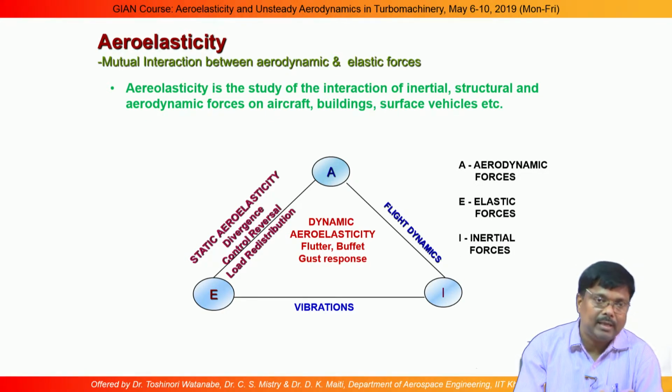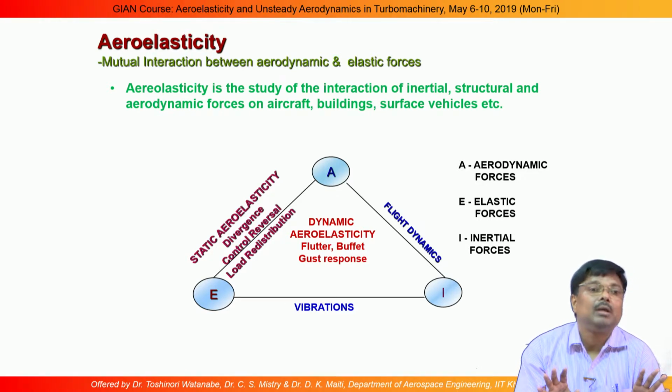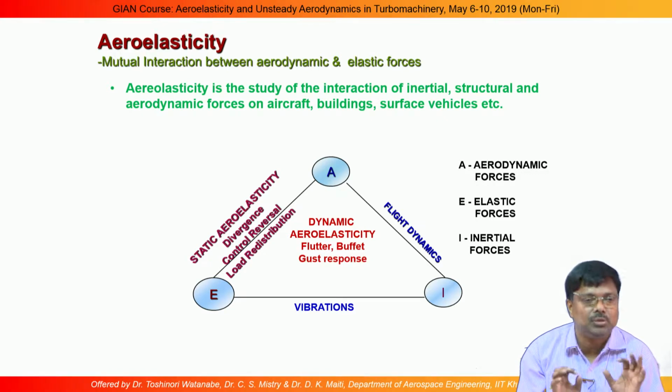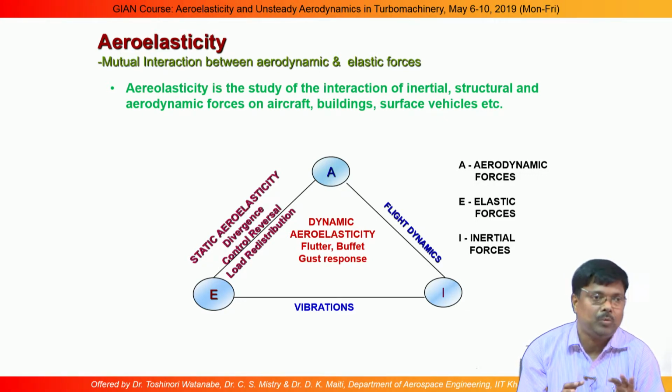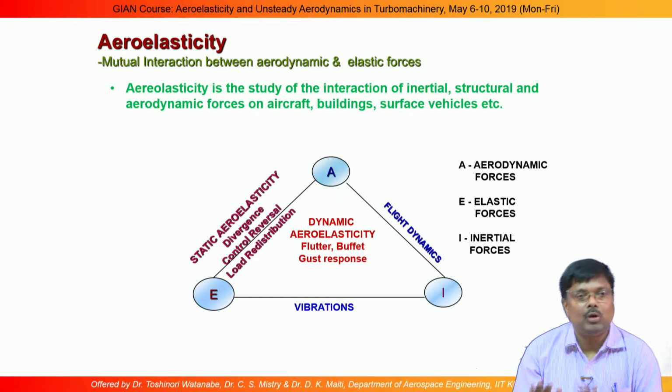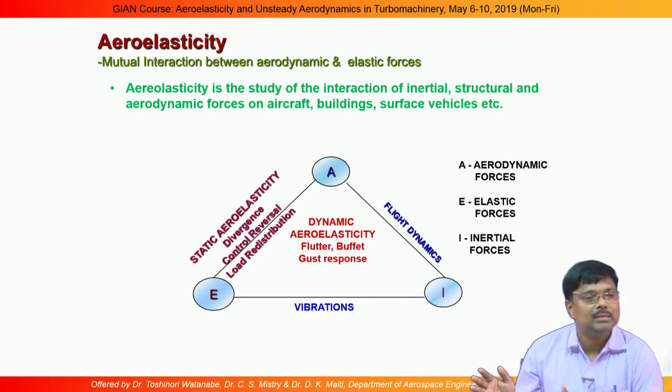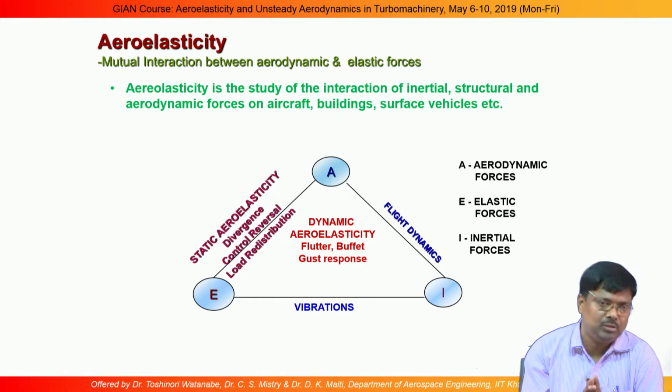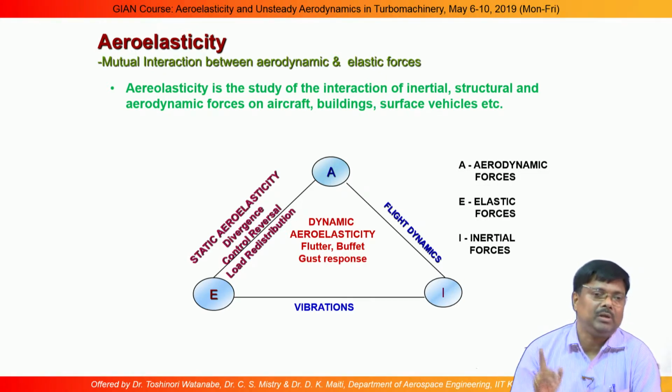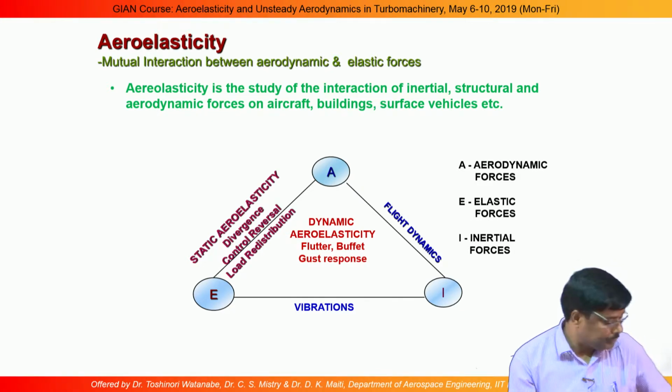Static analysis I can do on a physical model, but dynamic analysis would be very difficult and expensive, so we always do it in the modal domain. Gust analysis is done separately in the modal domain, and we consider it a linear elastic analysis. So we superpose these two displacements together and then monitor the stress values at different parts of the aircraft, whether they are within allowable limits or not. Okay.